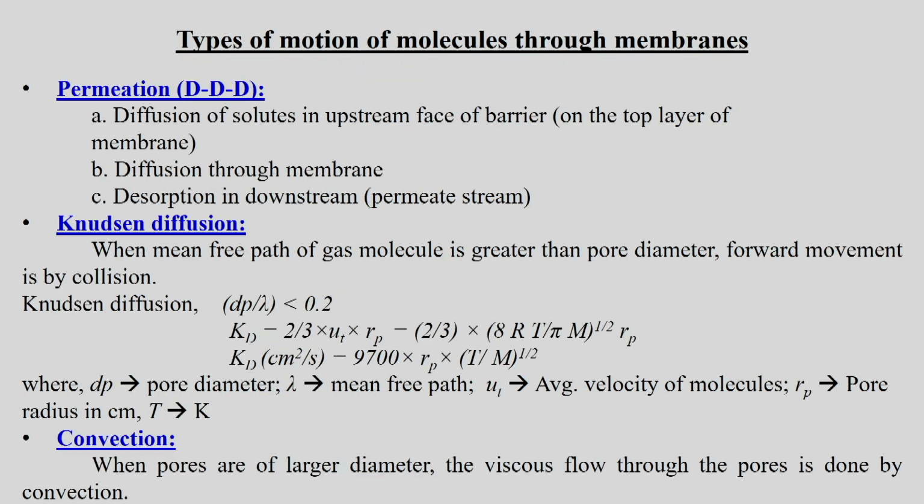Like this, the types of motion of the molecules through the membranes, that is permeation, we can say the DDD concept. Like this: diffusion of the solutes in the upstream phase of the barrier, and then diffusion through the membrane, and then desorption in the downstream.